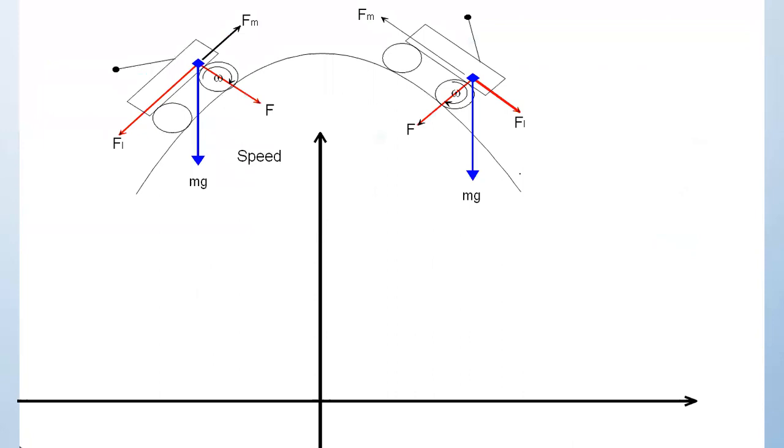Let us take an example. What happens when a truck or a train is moving up the hill? Once it reaches the top, the load torque becomes zero, and then coming down, the speed increases to a large value. So here regenerative braking operation is possible during the downhill.